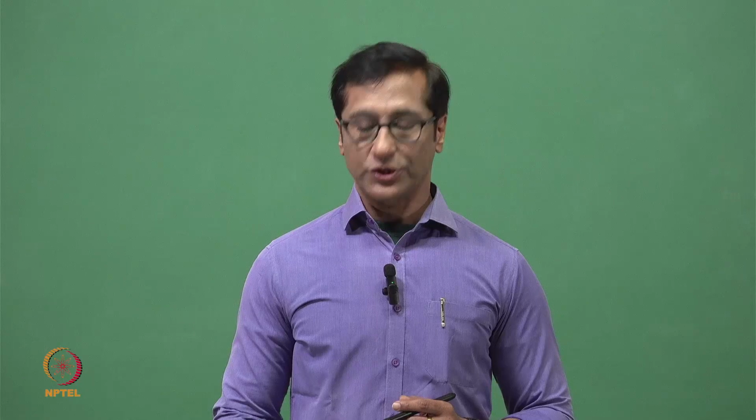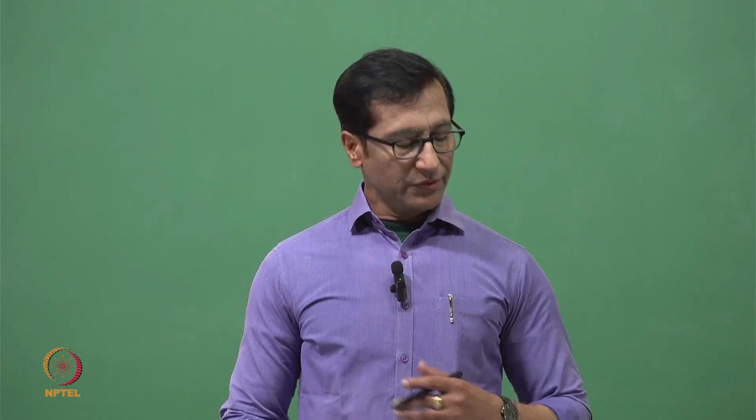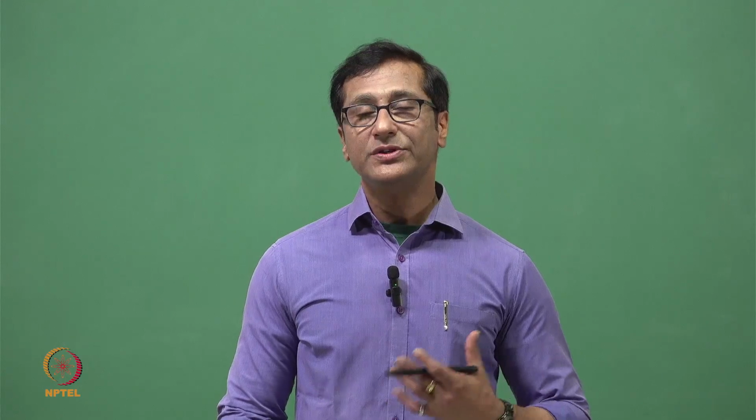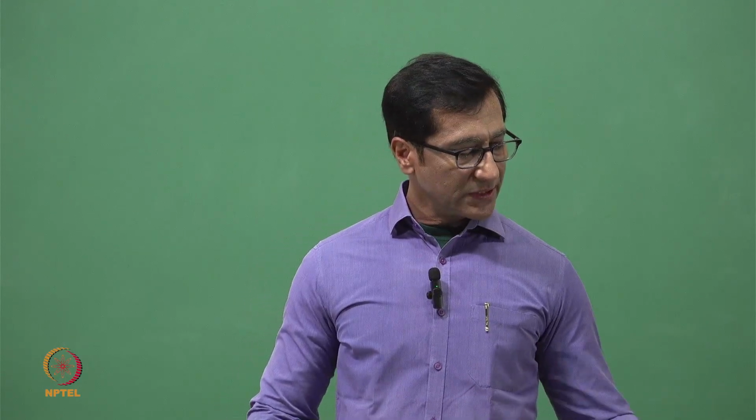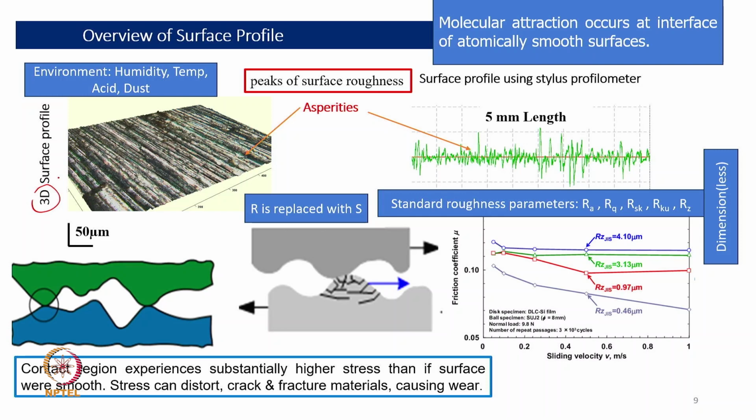We can incorporate a specific film thickness in this case to get better results, or a better representation. We have already studied that we really require surface roughness. When we measure surface roughness, we have two options. We have a 3D surface profilometer, where the whole surface is measured, and a 2D stylus profilometer, where we get a 2D curve.